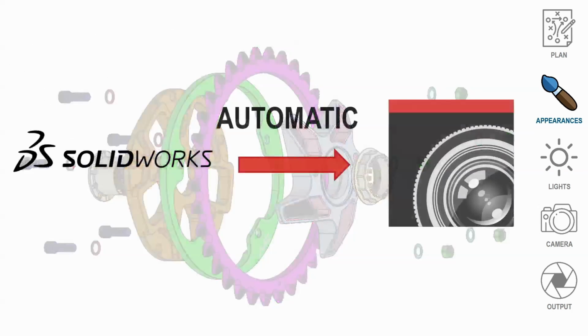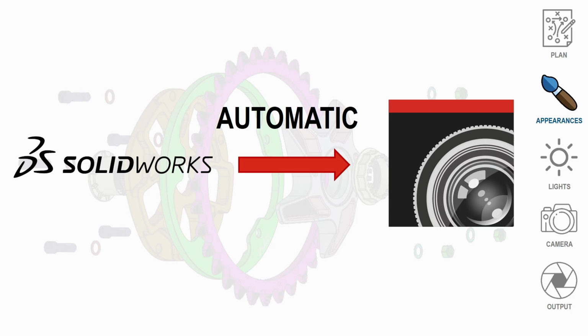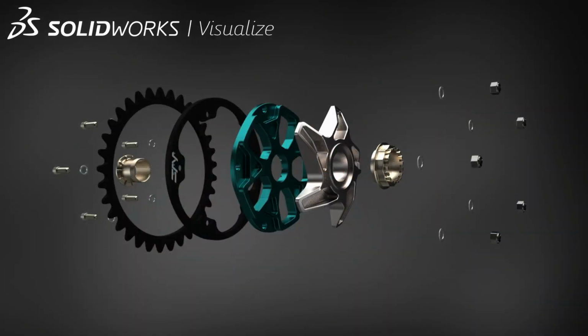So from there, once I get to that process, I then import it using the automatic settings into Visualize, and then that turns into whatever rendering you're working on. All right, so I just end up swapping out those appearances with drag and drop to whatever appearance I want. And again, that gives me full control over what this appearance is and what that appearance is. I have these hardwares grouped together, and this appearance is set to a different appearance than this, which is hard to see on the screen. But you've got a lot of control over exactly what it is you're trying to do.